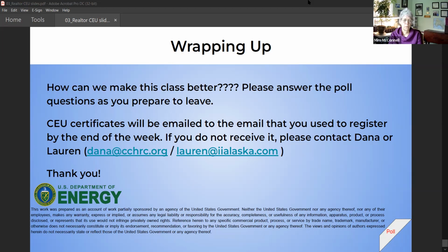So it just depends on what your air is like, and how that affects how often you have to clean them. Yeah, that's a great point, Mim. I've seen people come up with custom filter rigs for their own ductless mini splits for people who have woodworking shops. But the main thing is we got to provide adequate airflow, whether that's on the indoor side or the outdoor side. A lot of people think that ductless mini splits are ugly in general, and they're like, oh, I'm going to put something over this.